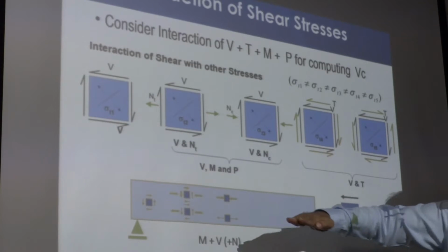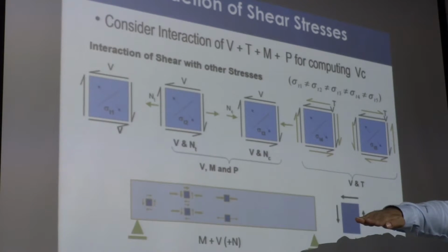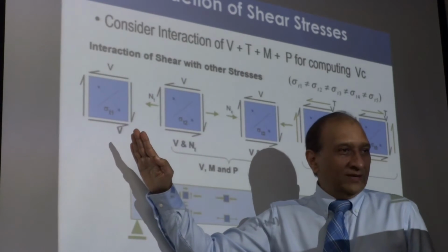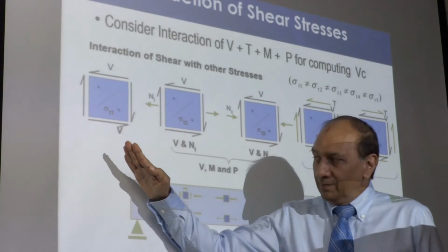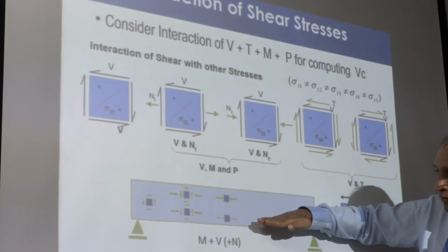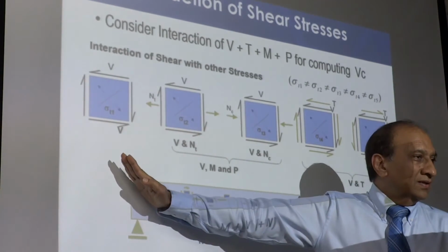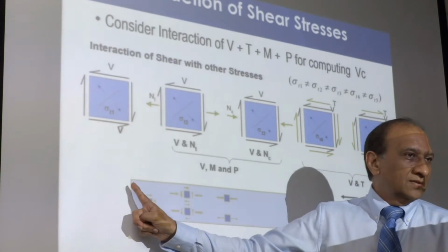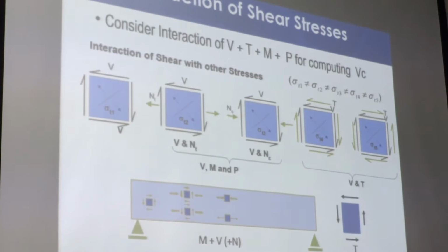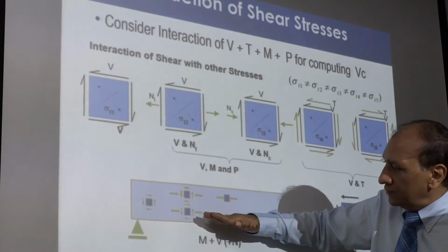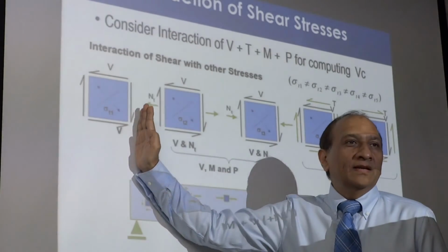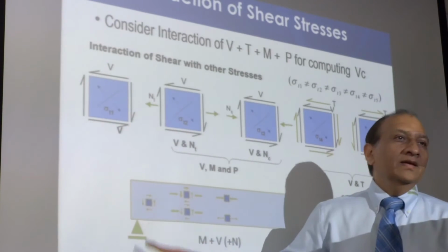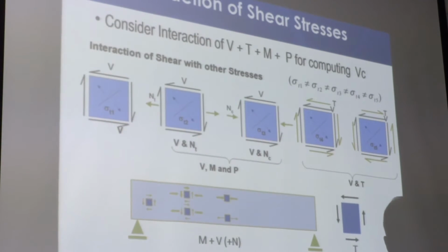In the middle, the tension is like this, right? Completely horizontal because there's no shear. This location, it's a 45-degree angle because there's no bending moment. In between, it will be like this. So it has to go from horizontal to 45-degree and exactly above vertical. Correct? Because stress must be vertical then, close to the reaction. So from completely horizontal stress position, we will gradually go to a completely vertical position of the support. Shear will be maximum when we have 45-degree angle.